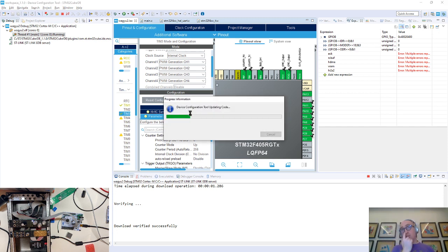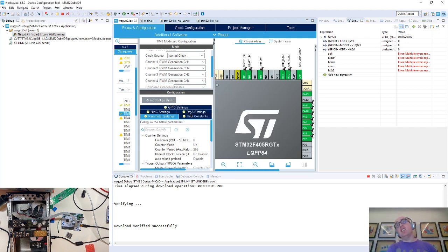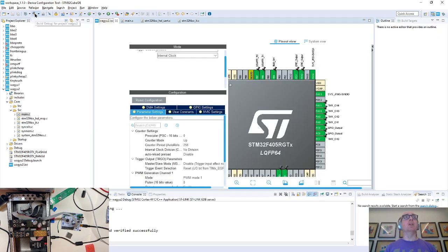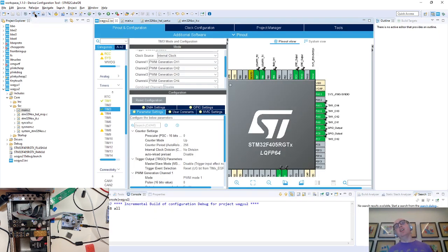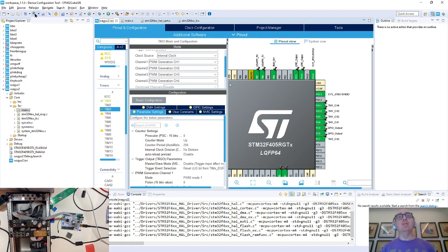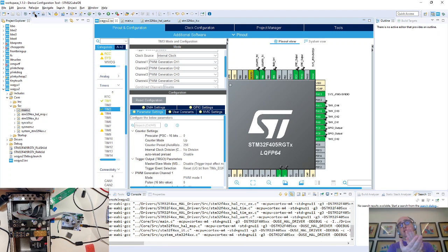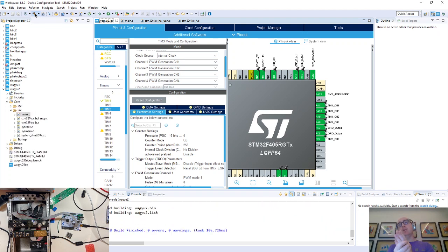Now, they should all just be PWM, but with a 0 period, which means they're low, which is the right way around to light the LEDs. So we'd expect a row of LEDs to light up, but hopefully to spoil it, they won't, because I've made a mistake. But I made this mistake yesterday, so I thought I'd make it with you. I've got my one column pin high, configured in GPIO, which is the first column. And I've made all of the rows, which are PWM controlled for brightness, all 0. So they should light the first 8 LEDs.